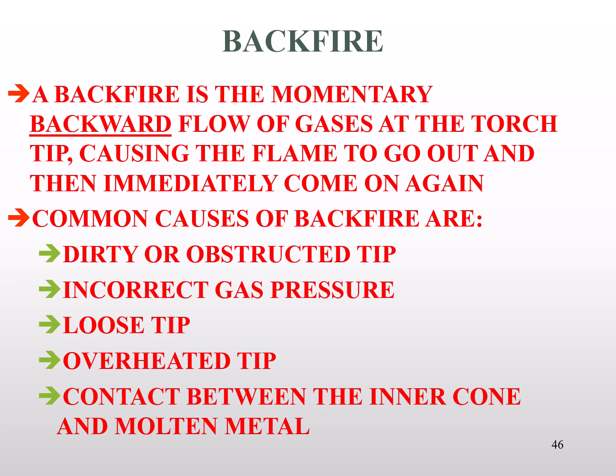Also, if you dip your tip down into the molten metal puddle of the weld, that can cause a backfire. Now, a backfire is not dangerous. However, if it backfires because you touch your tip, it could push some of that molten metal out and cause it to burn holes in clothes. So therefore, don't wear clothes into this lab specifically if you're not willing to get a little bit of damage. Good clothes can get ruined in that process.